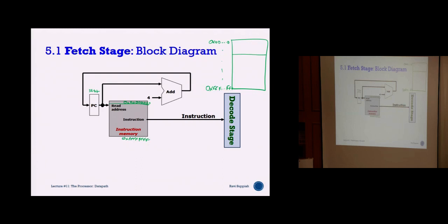By having a, I'm not sure whether you've heard this term before, reset vector. Have you heard this term before? Okay, maybe some of you have. The reset vector is basically where my processor should start executing from when I press the reset button. When you reset your handphone or some device, how does it know where to start executing the code from? It must be a fixed point. It cannot keep changing. Most processor architectures are such that the reset vector will usually be address 0.